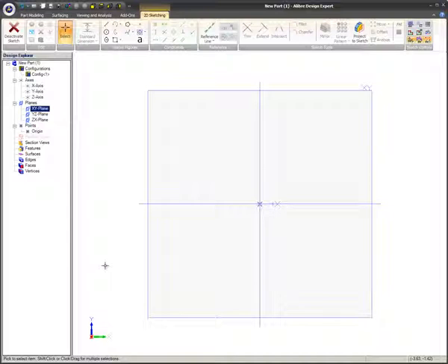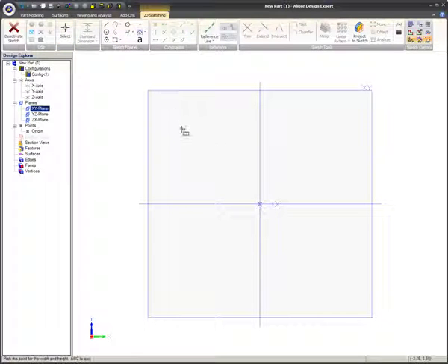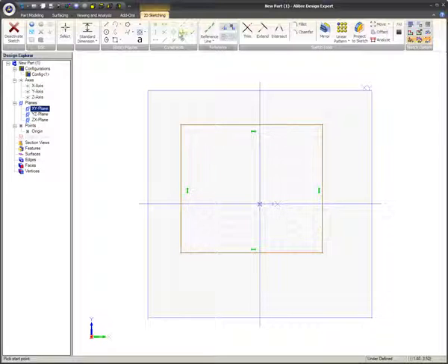When sketching, it is helpful to have status hints turned on so Alibre can tell you what it's looking for during the sketching process. Figures may be constrained automatically as they are sketched, or may be set with constraint tools from the 2D sketching ribbon. The available sketch constraints are fixed, symmetric, co-radial, collinear, equal, coincident, perpendicular, concentric, intersection, vertical, horizontal, midpoint, tangent, and parallel.